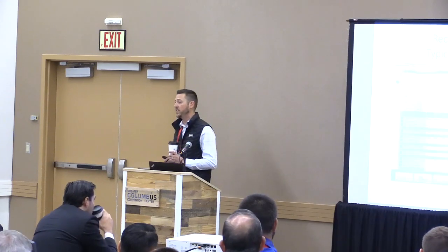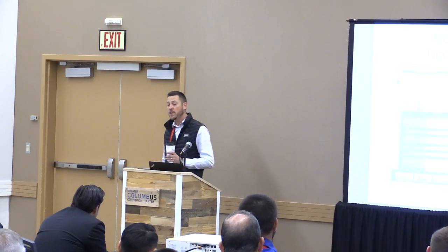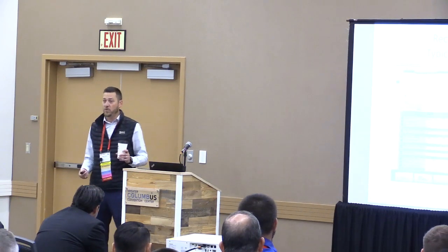And so some people in the room will say, hey, that's a poor use of time with a vacuum furnace to be running it at 1,000 degrees. It's a high dollar piece of equipment, and maybe I want to run it in a nitrogen temper or something like that. And that's something you guys have to weigh. If you have extra capacity in your furnace and you're able to run it like this, where an operator can walk away for a very long cycle and that furnace can operate in a totally automatic function, then you're saving time, right? If you're not actually using your furnace 24/7.